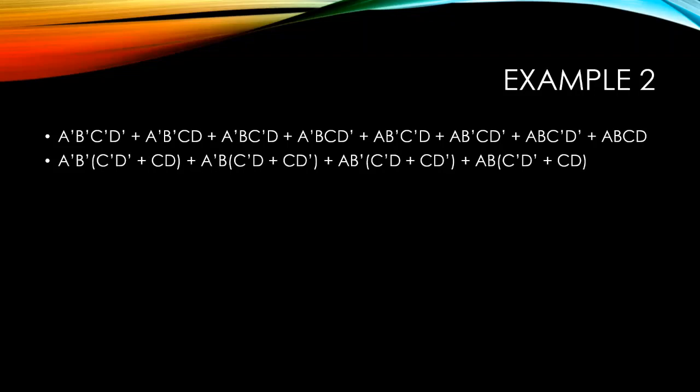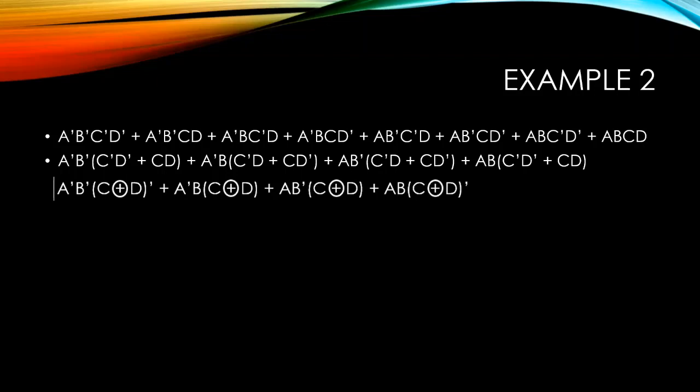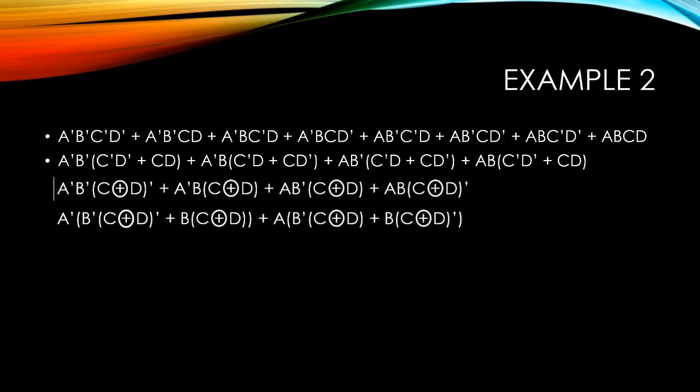And inside the parentheses, it could be either XOR or XNOR. So just apply our knowledge about these two gates. Rewrite the equation. So we have this. And as you can see, okay, we could factor a variable on the first two terms and also on the last two terms. So factor out A naught for the first two terms and A for the last two terms. So this will be the result.